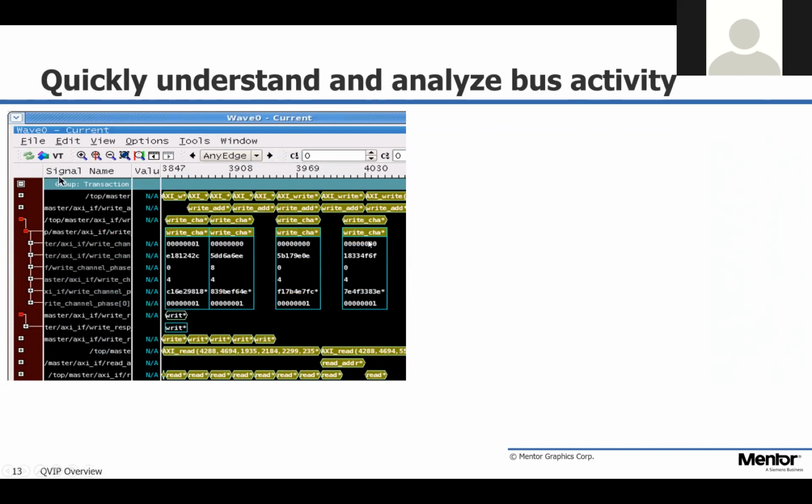So debugging at that level, especially on things like a PCIe bus, where it is a 2-wire interface that is 3,000 clock cycles long to complete a transaction, you probably do not want to have to analyze that serial data stream to make sure that the transaction you were expecting happened. Instead, our verification IP will monitor that, and it will pick out that a write with these parameters happened.